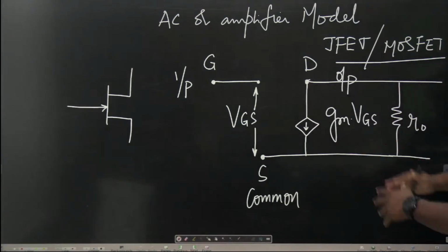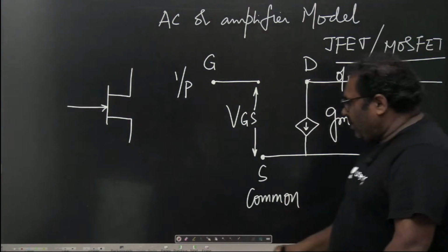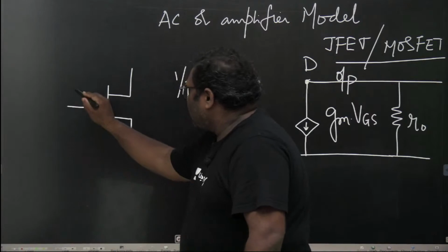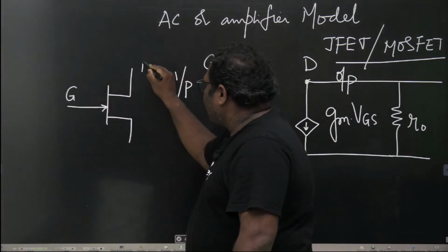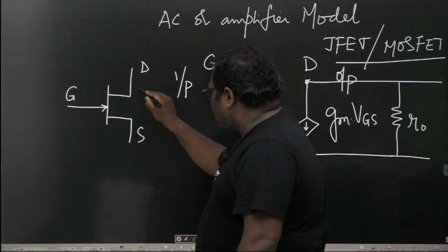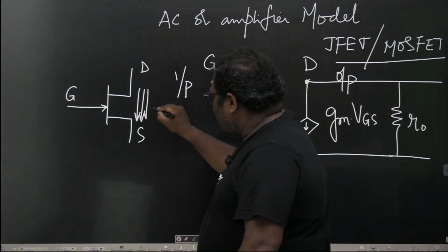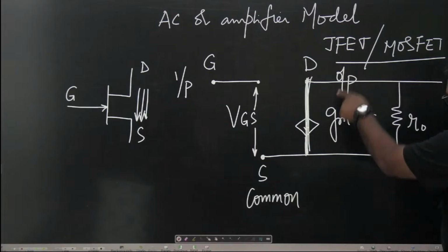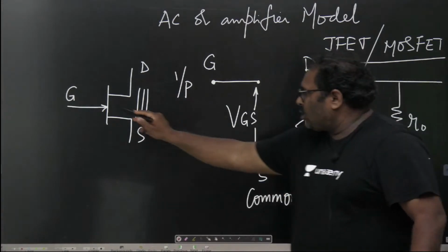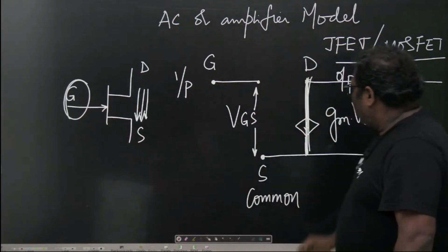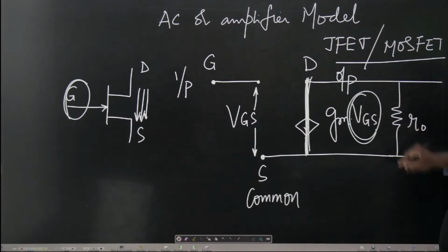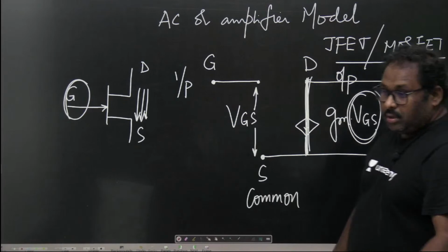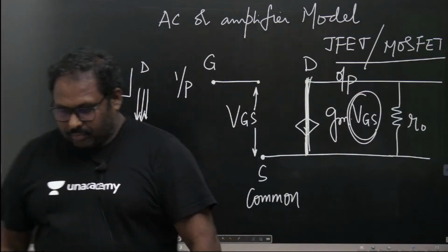So this forms your final circuit model. Between your gate, drain and the source, there is a flow. There is a flow between the drain and the source. This flow is being controlled by the gate. Non-ideally, there is also resistance. This forms a circuit model.